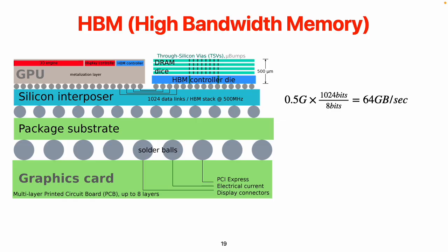Some people, I don't want to say who, but I did hear some professor say that 3D die stacking would help alleviate the Dennard scaling problem. I counter-argued that, and I got confirmation from Intel as well, that actually it will make it worse. Because in the past, it's just one layer, so no matter which layer you are, the heat directly goes out. But right now, it will affect another layer. What does that mean? The lower layer, because the heat goes up, will heat up another layer. So it actually adds up the heat.